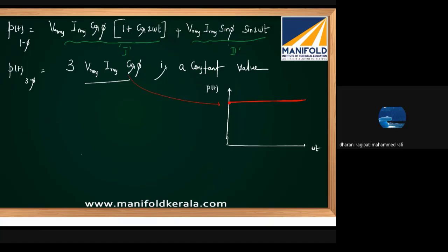That's why a three-phase system is so rugged, so stable, because the instantaneous power transmitted from source to load is constant. It is not fluctuating. That's why if you start a single phase motor, you require some support from a capacitor or some other element because of this vibrating nature. If you start a fan, it will make some thud and then start. Whereas when you start a big three-phase induction motor, it runs smoothly. It has longer life. It is more rugged.